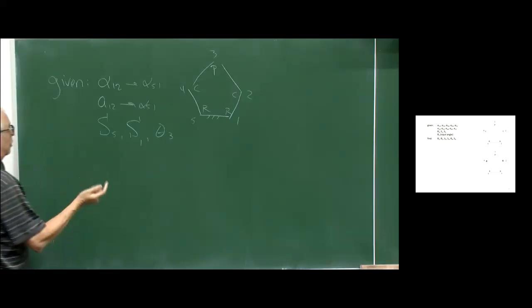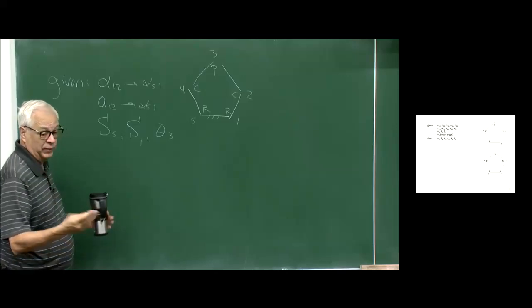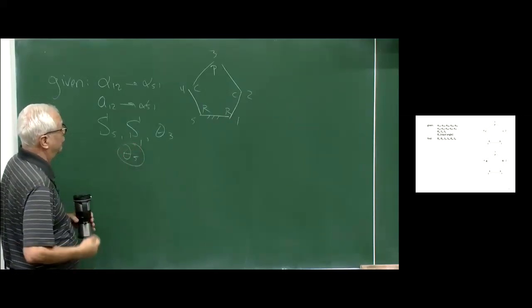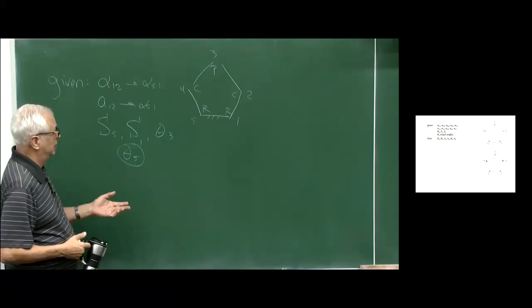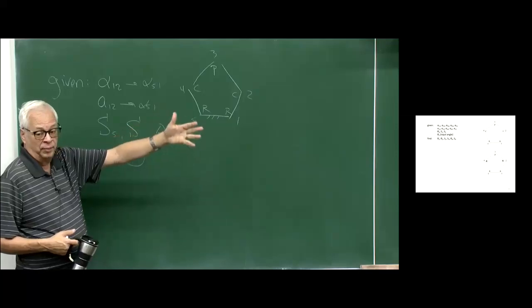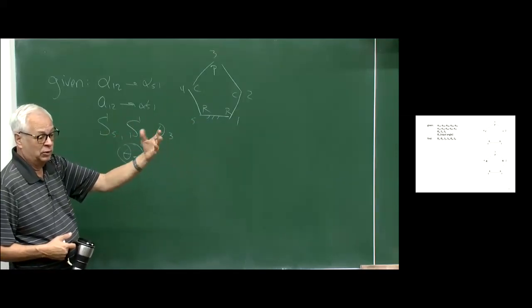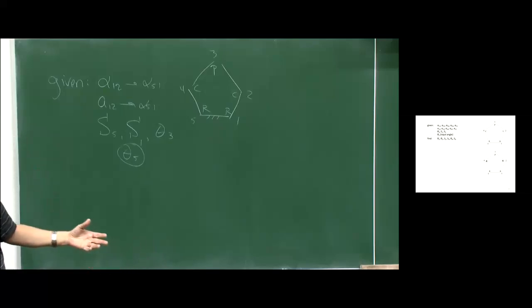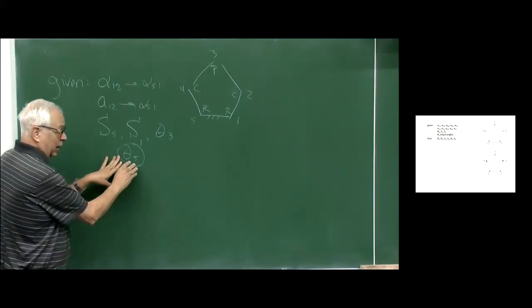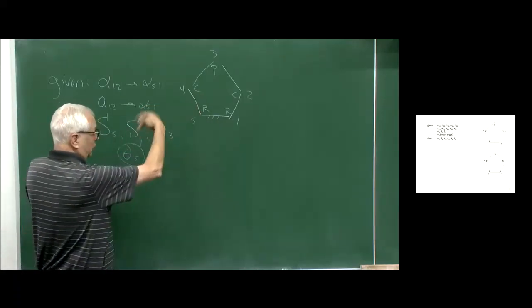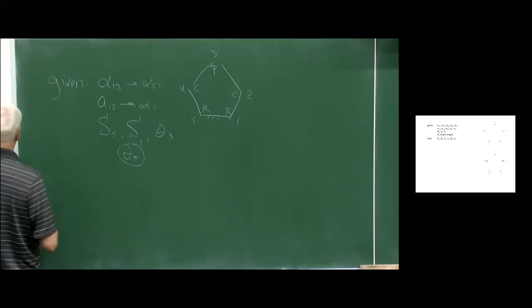Oh, it's a 1 degree of freedom device, so I have to give you one of the inputs, or one of the angles, and we're going to go ahead and say theta 5. I'm never going to switch this up and say the input is, for example, this S4. I'm not going to do that because we're trying to do reverse analysis problems. When we close the loop, remember when we had the 6 revolutes, we knew theta 7 was one of the closed. You're going to know one of the thetas. So we're always just going to do that, given one of the thetas on these problems. I'm not going to switch it up and say, oh, I'll give you S4. You should be able to solve it, but we're not going to do that.